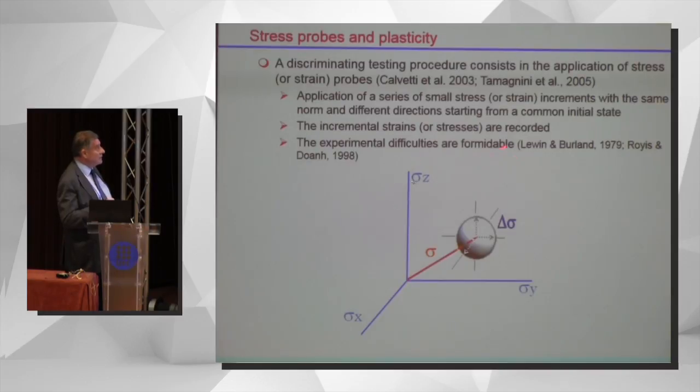This has been done experimentally, but it's very difficult to always get the same sample at this point, and then the strains are very small, difficult to measure. There are time effects that affect the results, so the tests are difficult to do, but it is not that difficult if you represent the granular material in the computer. And that was done some time ago by Calvetti, Tamagnini, and co-workers. Here, what we are going to introduce, and this is new, is the fact that the particles are crushable.